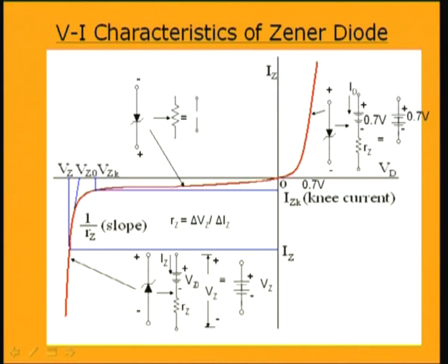This Zener diode is almost like an open circuit, and the corresponding voltage is Vzk for this knee point. The center of this knee point corresponds to Izk, Vzk. That point is significant in the sense that before it is reached, the reverse breakdown phenomenon is not occurring, and the Zener diode only has the reverse saturation current, which is very negligible. So, the resistance is very, very high. After this knee point is reached, the current rises very sharply.